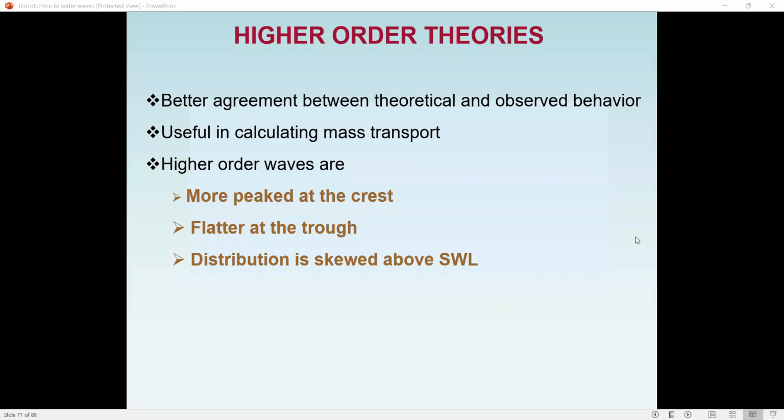So, apart from the linear wave theory, when I come to the higher order wave theory, there is a better agreement between the theoretical and observed behavior, useful in calculating mass transport. And the higher order waves are more peaked at the crest, flatter at the trough, and the distribution is skewed above the still water level.